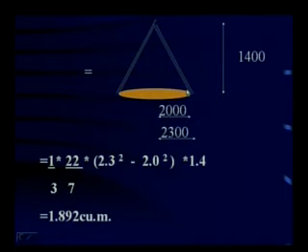So can you calculate the volume of a cone? This is the blanket, these 2 lines. Between these 2 lines, the blanket is there, that is called revetment. The thickness of the revetment is 300 mm. So how do you get the volume directly? 1/3 pi r square h is the formula. From the outer volume, deduct the inner volume. So you get the thick layer of revetment. Is that okay? The outer calculation you do with 2.3 meters, and the inner volume you get by calculating with 2 meters. Subtract both and you get 1.892 cubic meters.